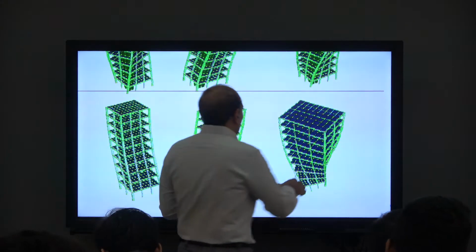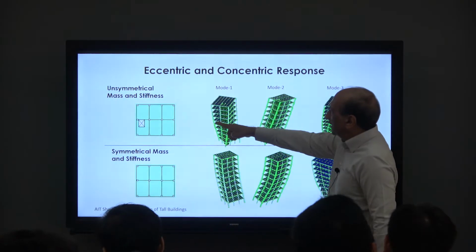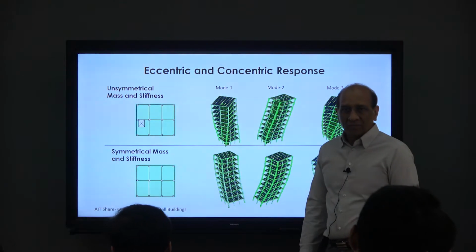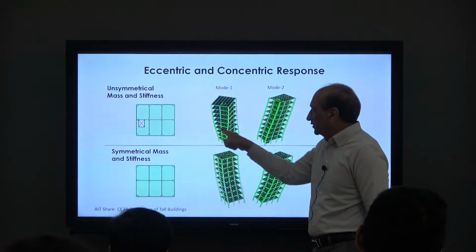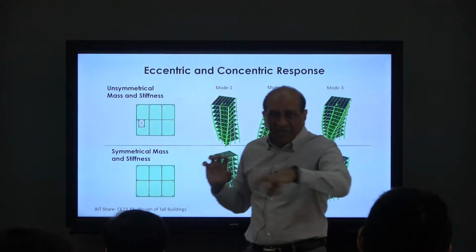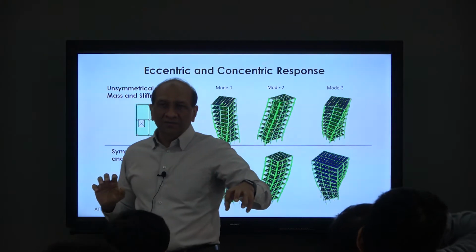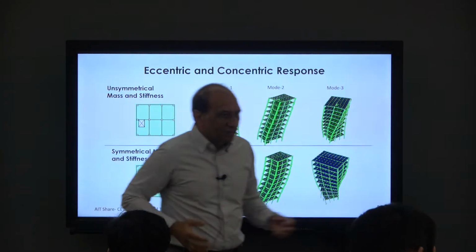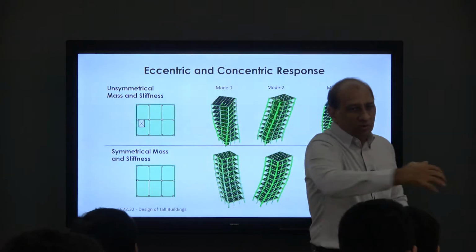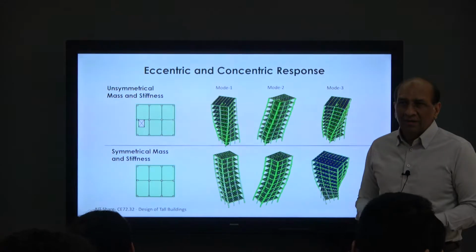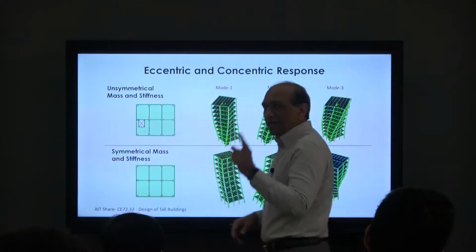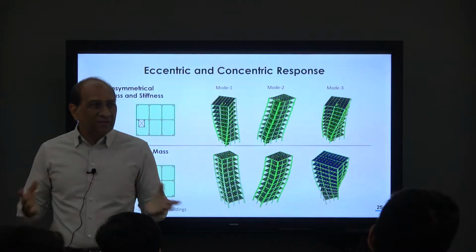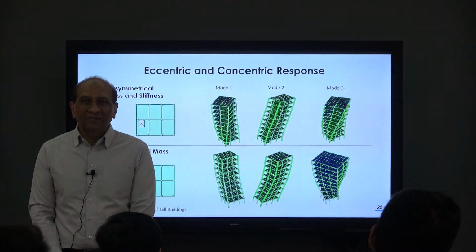So that's also very important. And if the structure is unsymmetrical, the first mode can be torsion, right, because the shear wall over there shifted the stiffness center. So now the mass center and stiffness center are not aligned, so buildings start to twist, in which case the first mode will be torsional even if there is no eccentricity of the mass of the